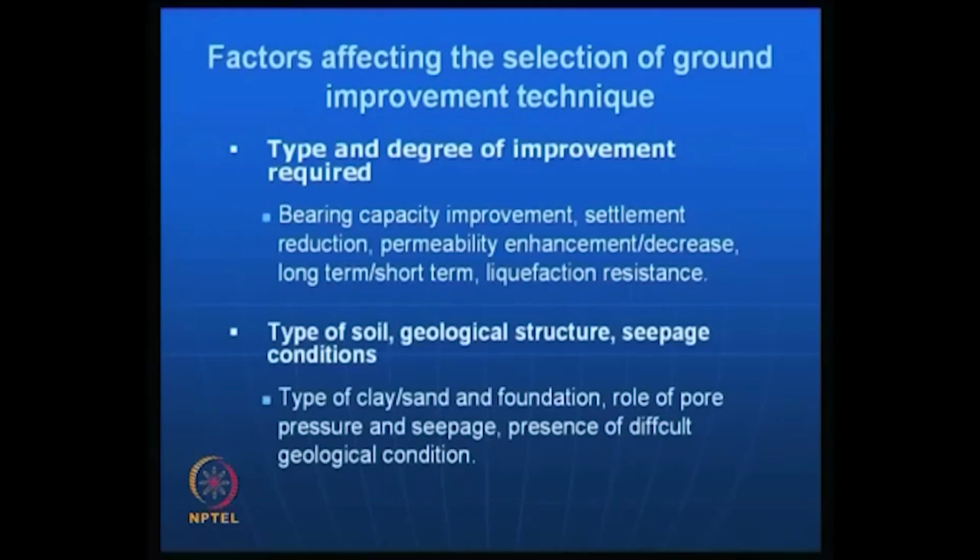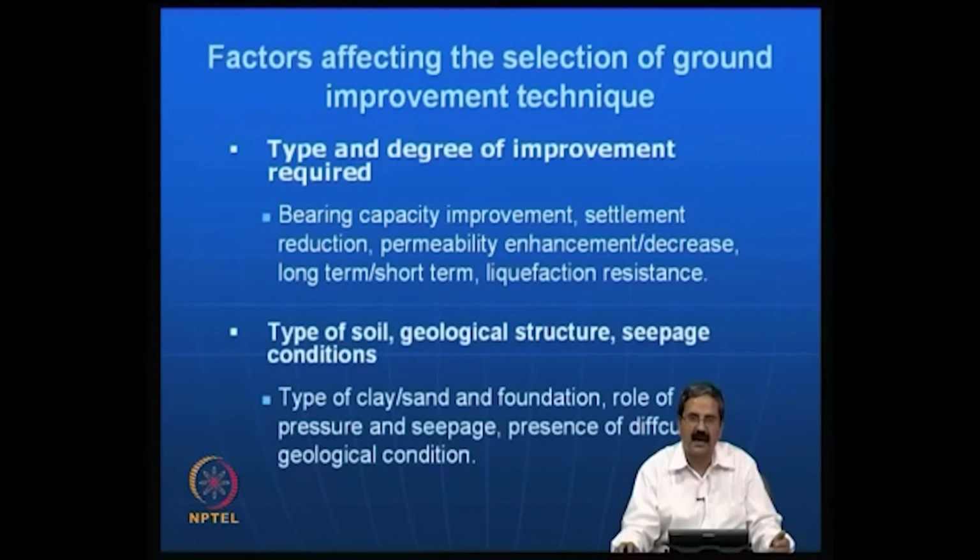For example, in one case the bearing capacity of the soil is only 10 ton per meter square, and then you would like to make it 30 ton per meter square. So, 30 by 10 is called the bearing capacity ratio. I know exactly what I need, like I need 30 ton per meter square for that area. So, I will design this in a proper way such that I will get that 30 or 35 and even conduct a plate load test to see that I get the same thing, because you have to finally confirm to the people that you got this number like 30 ton per meter square, otherwise the technique may not stand at all.